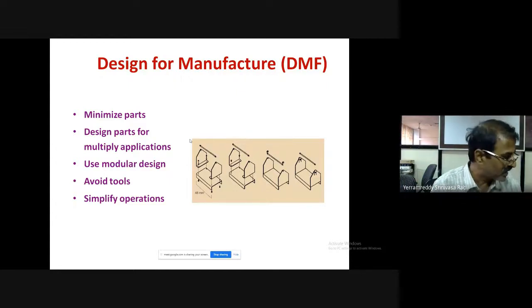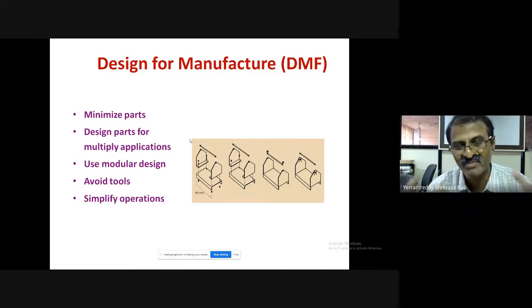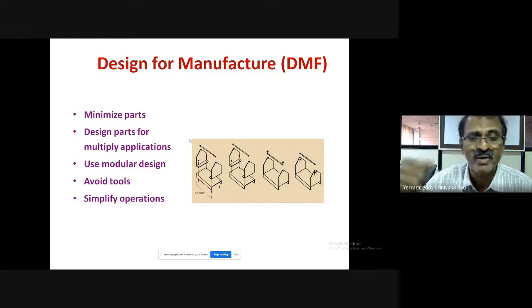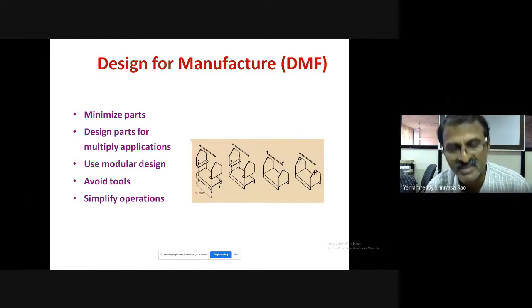Like in my case, the cabinet part, I want to make it low cost, but at the same time modular, lightweight, carryable. So you have to identify that, instead of that big wooden box or metal box, nobody would like to carry them. So you have to look for design for manufacturing aspects and also the transportation part.